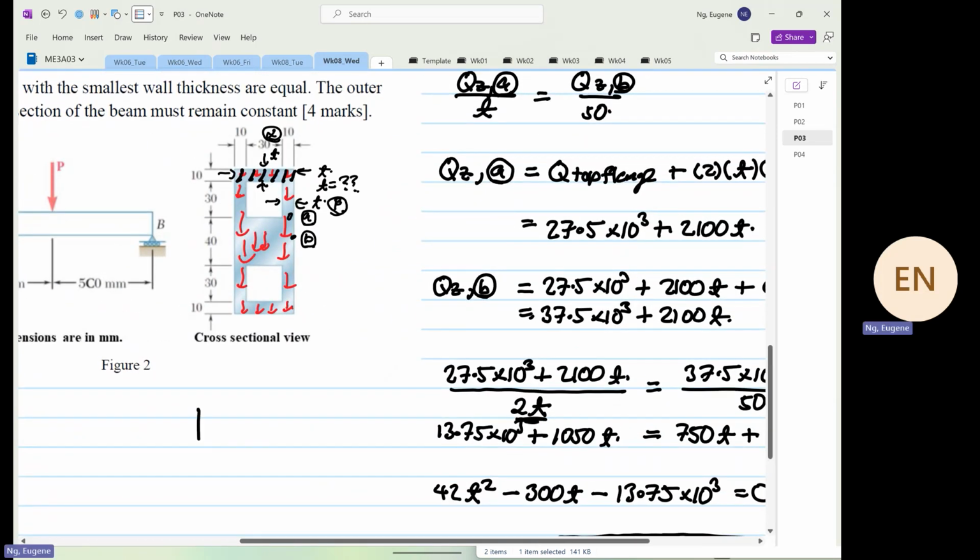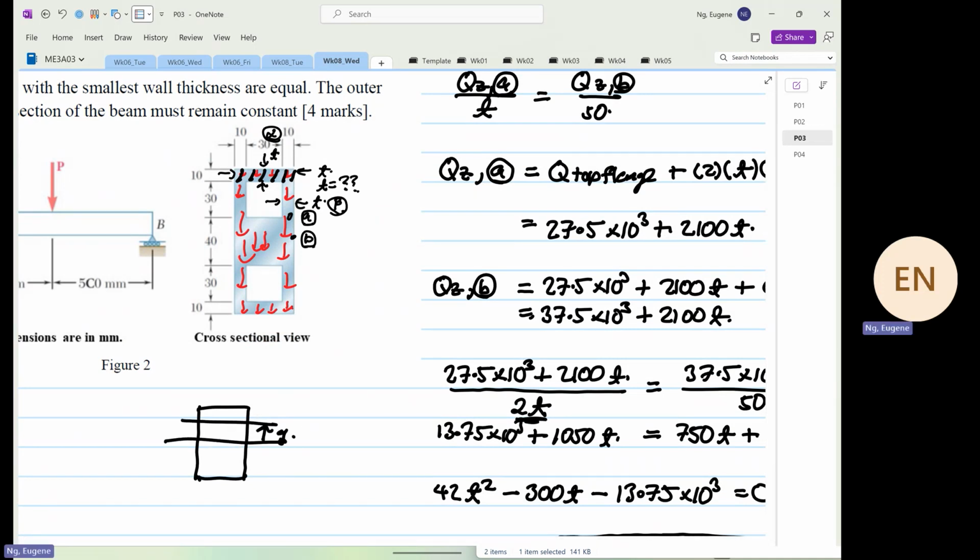If you look at the equation, the variable cuts across y in this direction. It does not care, meaning it's the entire thickness over the entire length. If I draw a straight line across with a variable y, you have to consider two thicknesses because it cuts across two thicknesses. The solution manual doesn't show that. Sometimes they do it, sometimes they don't. Let's standardize. Are we clear?